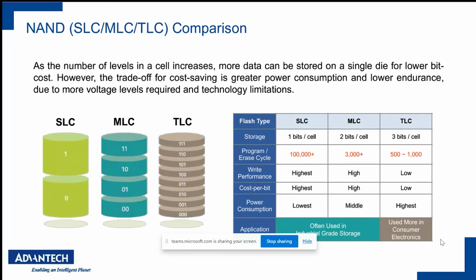A key parameter of SSD durability is the program/erase cycle. Basically, how many writes can a cell take? SLC is the best, at an average of 100K writes per cell. Ultra MLC is around 30K writes per cell. MLC is at around 3K writes per cell, and TLC at 1K writes per cell.